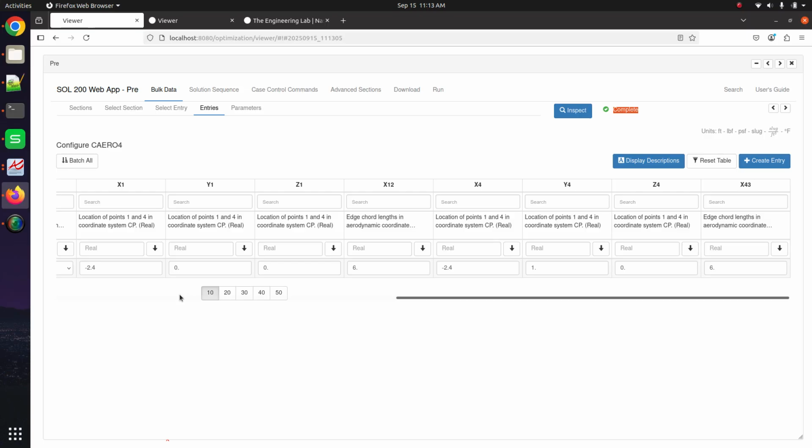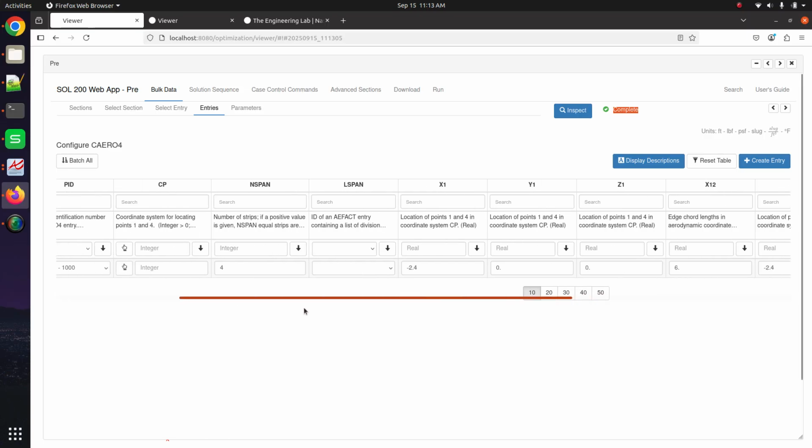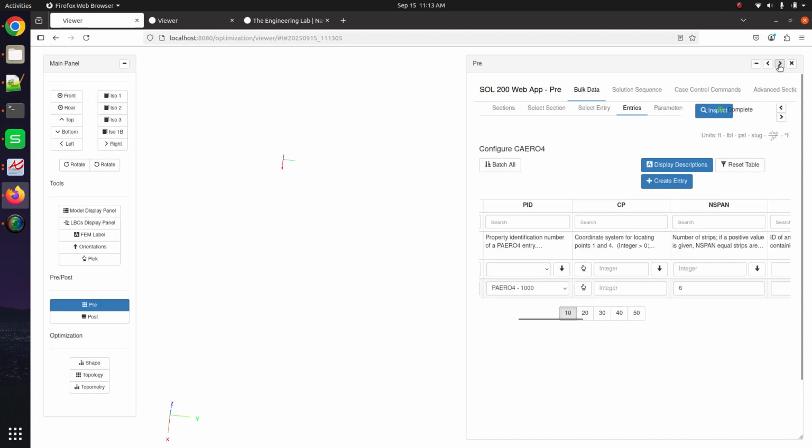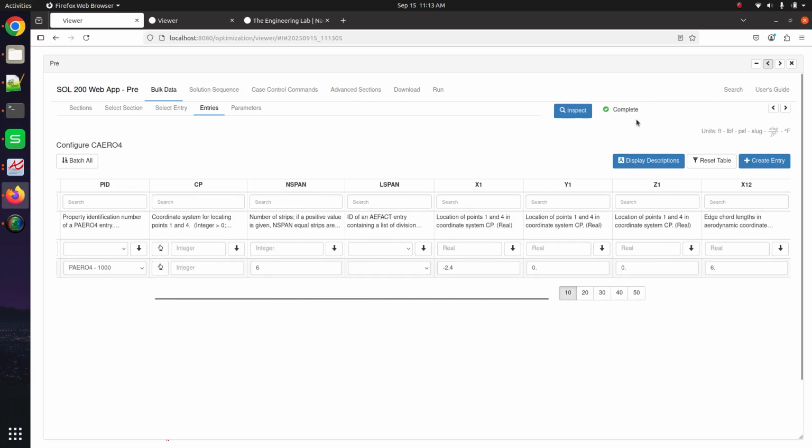It can run successfully. Now, suppose we make a mistake. Suppose I type in 6 here. You notice one thing: because I have not supplied enough data, the preview is blank here on the right. Now, look what happens when I try and run Nastran. I will get an error saying, hey, you're missing data. You have to provide the data. And here, magically, it still worked.